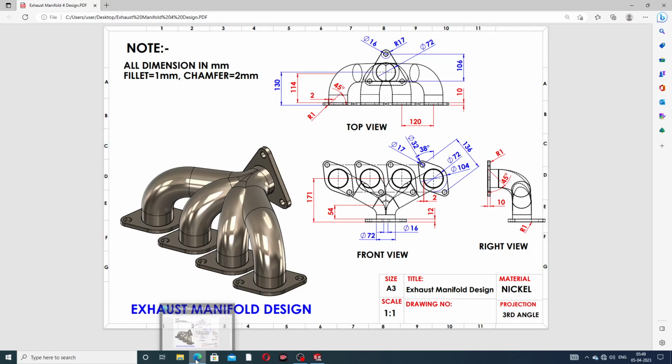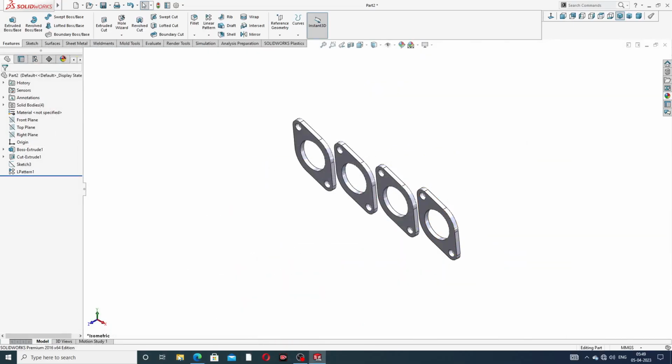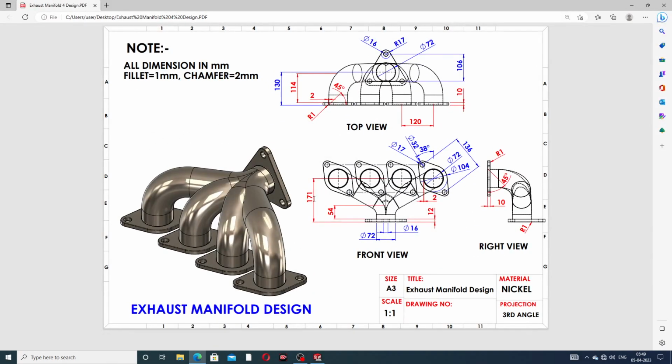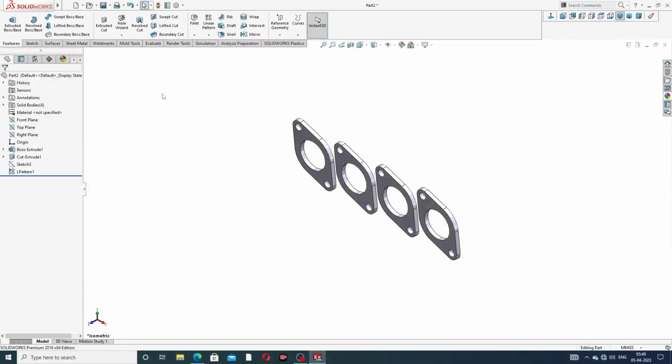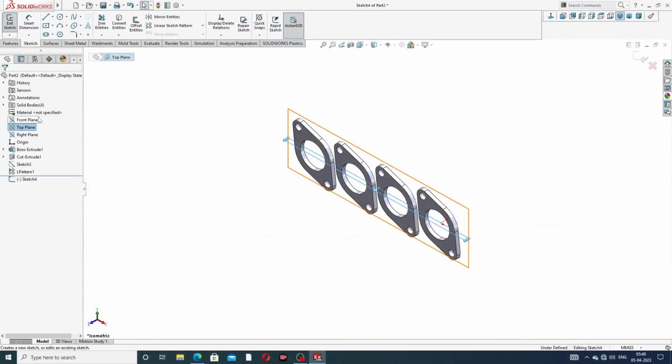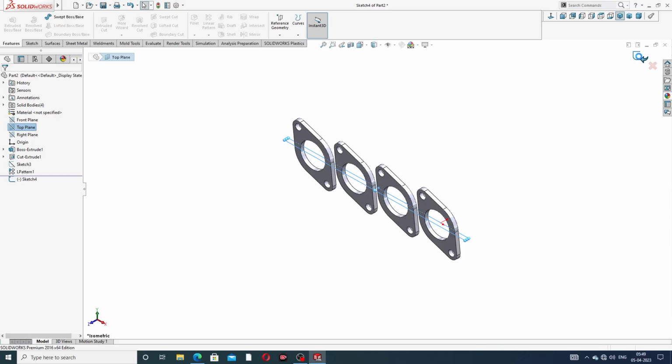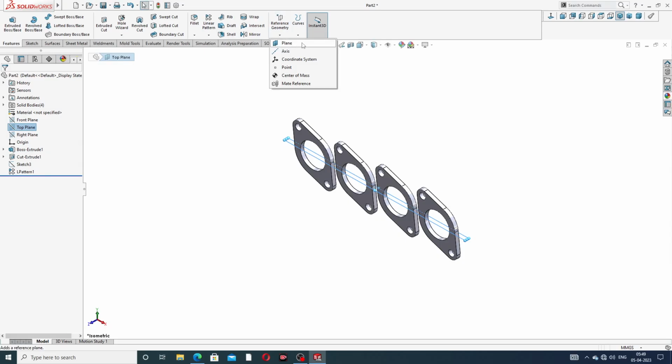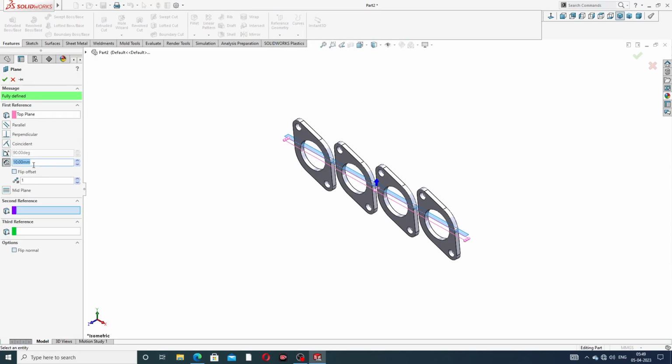Okay, and draw a, then use, okay, this is a very important point: use 171 millimeter. This is a plane created here. Okay, at first use a top plane, select the top plane and use the plane created here, and 171 millimeter, this is a flip side. Click OK.